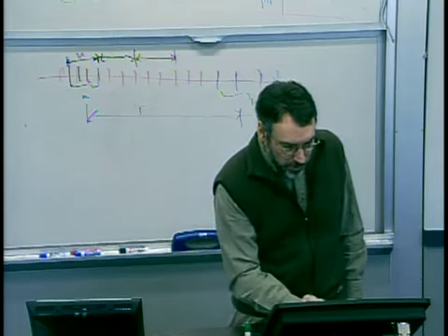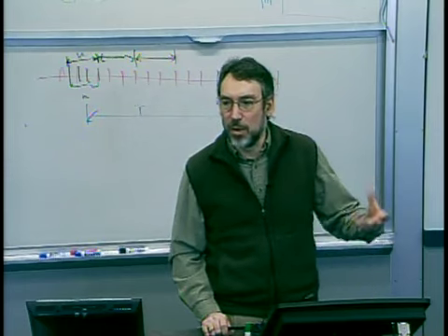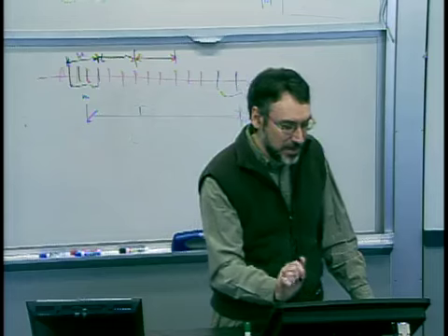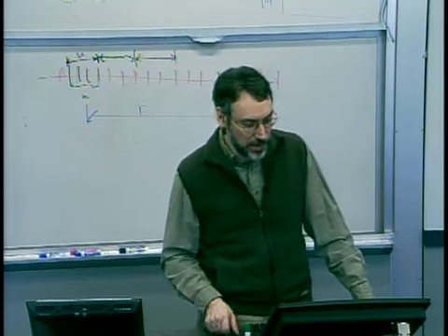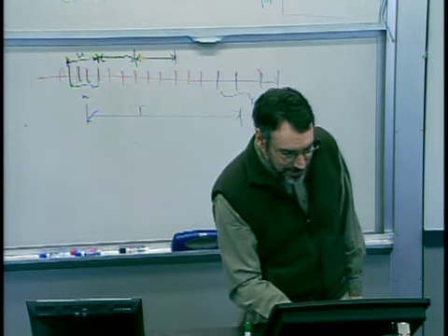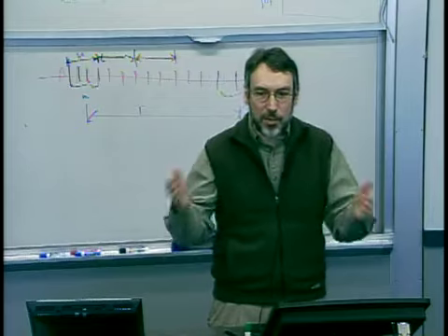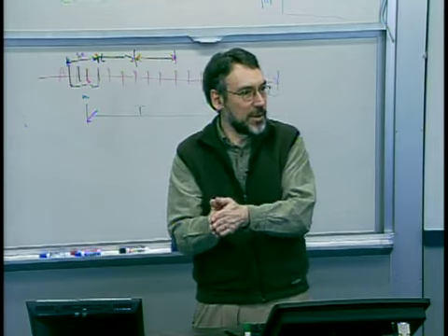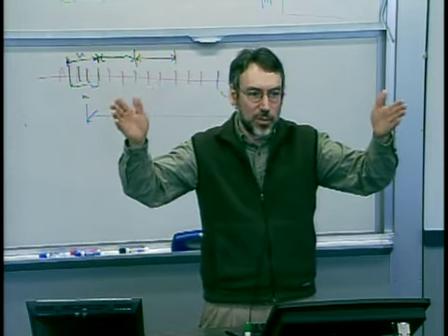The further I get away from x bar, I penalize more and more, not just in a linear fashion, but in a square fashion. And then I have some normalizer or some constant out front. What this basically says is you really want to be on target. So the more of your parts are right close to the target, the lower your loss function is. And then the further away you get, the worse and worse things are.